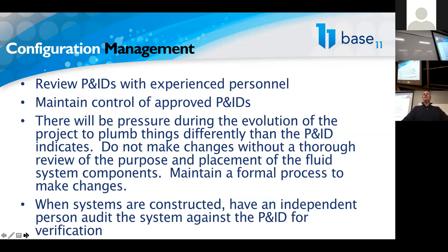Then we do a dash, and then the fluid that goes through the valve. So we have an MV-N2, MV-FU for fuel, MV-H2 if it's hydrogen, MV-H2O if it's water. And then the next designator is a number, so every component can have a unique identifier.